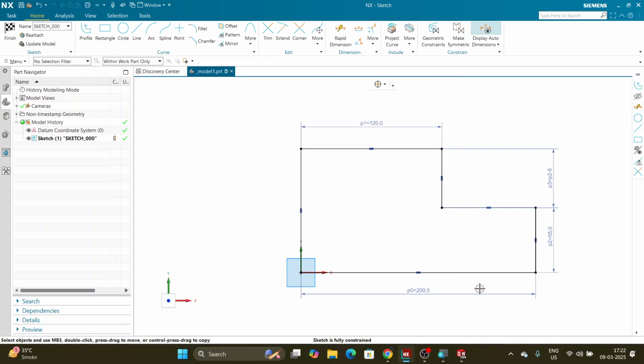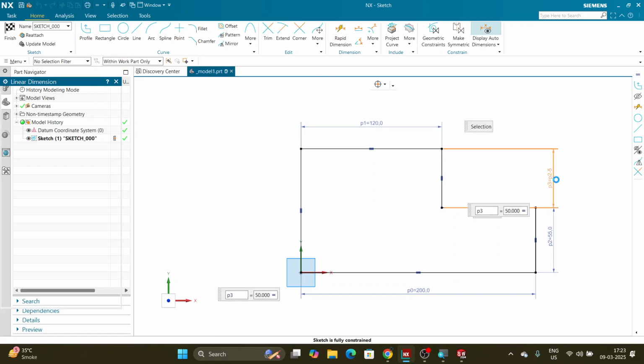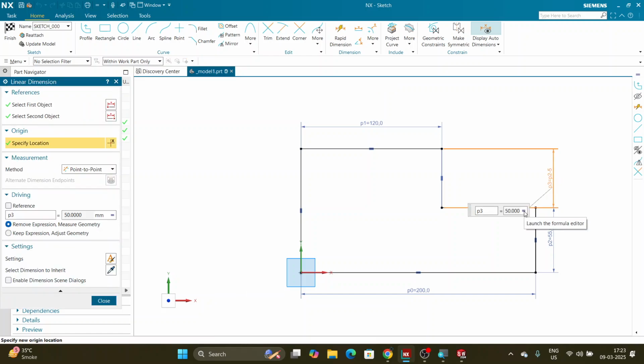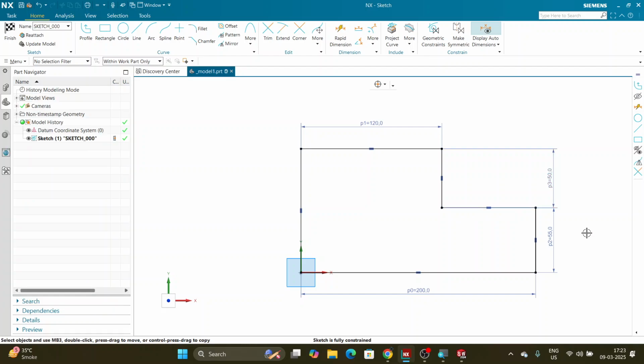And similarly, if you want to remove a relation from here on the screen, there is a way you can do that. You can double click on the dimension. You can see this equal to sign. If I click there, I can see an option here called make constant. If I use this option, it will remove that relation from there. See, now the relation is gone. Clear? So again, it was just an explanation of how to manually add some relations between the dimensions.